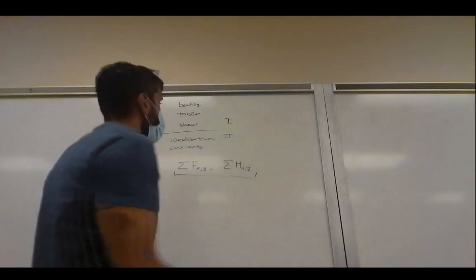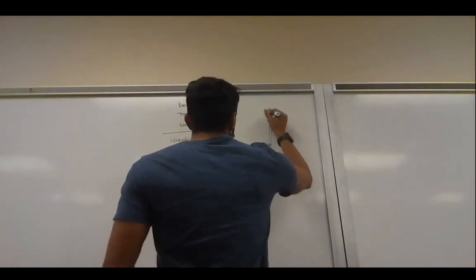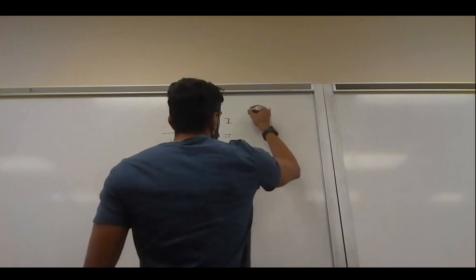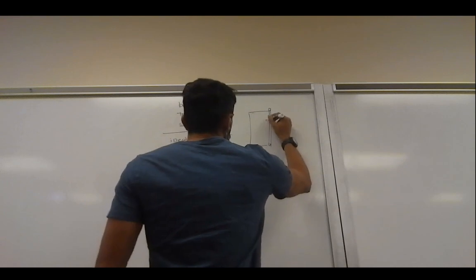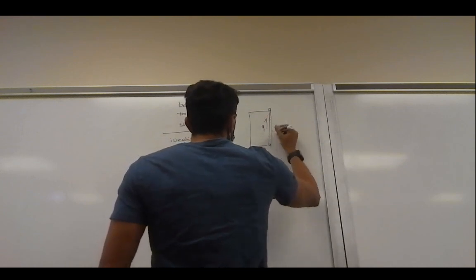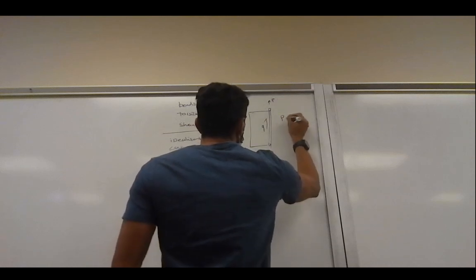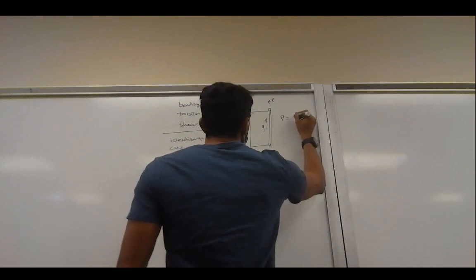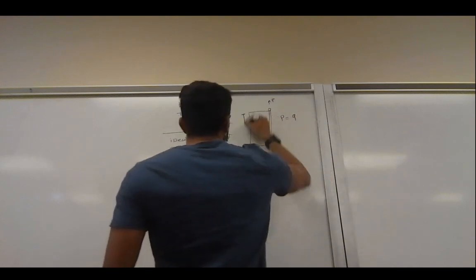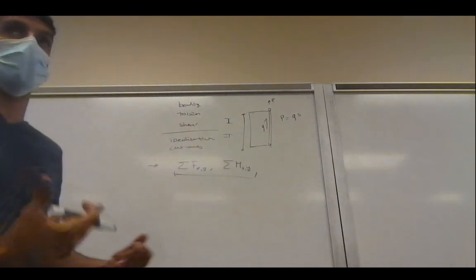And keep in mind, if you have a boom that carries all the stresses, say you have a stiffener, like in this case we had a panel, say this is the panel, and then we have a boom. Say we have a shear flow in this case, Q, and we have a force here, P. Then P will be, of course, in equilibrium with the shear flow in the panel, so P is equal to Q times S, this segment S, because shear flow times the distance traveled is our shear force.